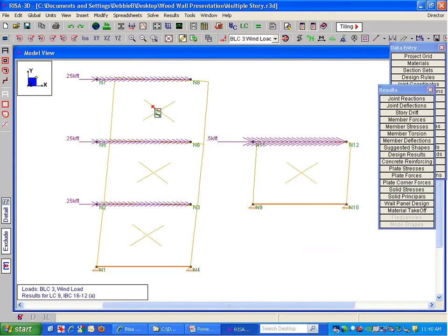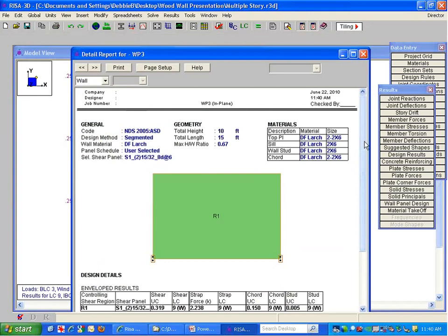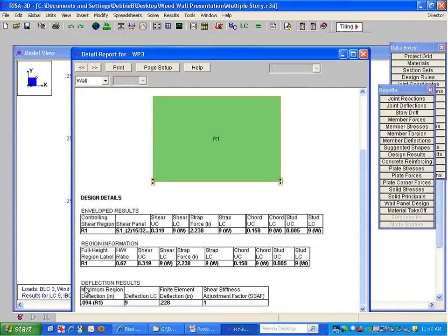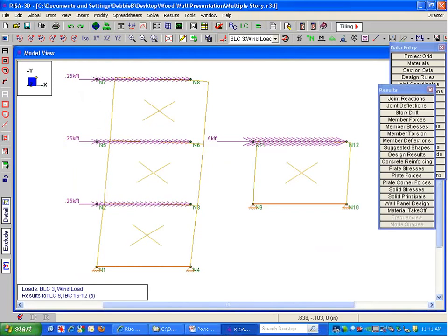And then even above that, we see another type of difference here. We're going even smaller on the deflection, so even if we did add in the hold down elongation, we're still not getting close to that finite element deflection. And so we want to maybe start to work with this shear stiffness adjustment factor. This is something you'd want to work with.